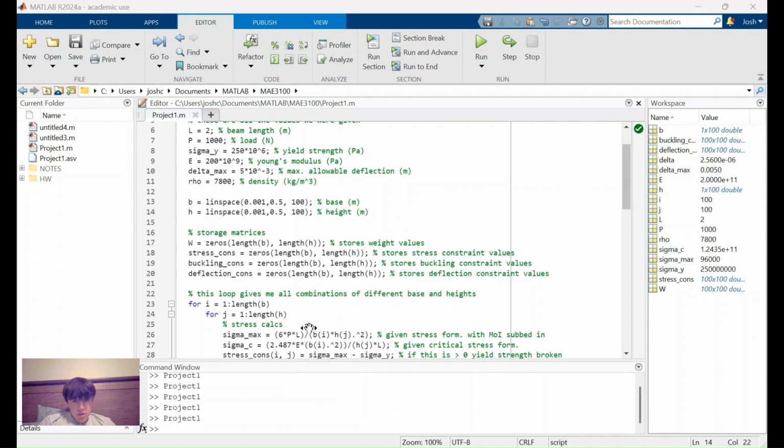So we're going to try and stay on this contour, but we don't want to go too far. If we pick too thin of a base and too high of a height, then we break our constraints. So we want to stay on the right side of these constraints and above these constraints. In this area is where we want to go. If we go over here, we're done for, and if we go over here, we break our constraints too. So we stay on this 378 contour, which is the smallest one we see with this amount of instances in this spacing.